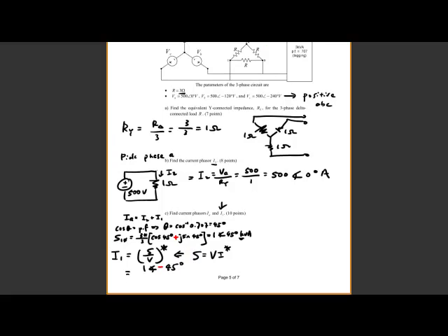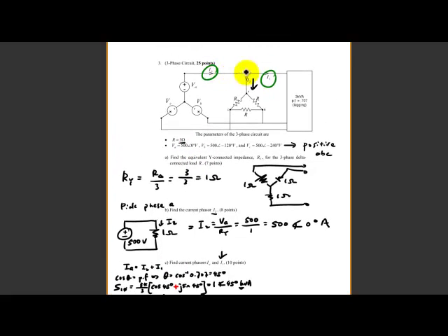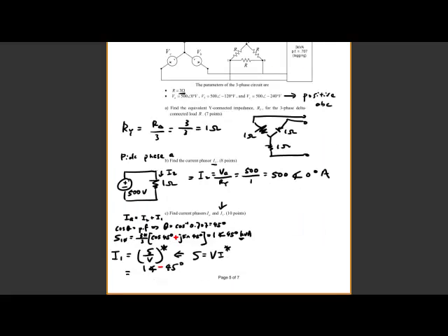And then you divide by the voltage. In this case, it will be just 500, because there is no resistor between these different parallel circuits. So all the voltage will be the same as the sending source. That will give you 500, right? And I think this is not just 1; it's 1k. Sometimes if you miss that, the solution will be totally wrong. So that will give me 2 with an angle of minus 45 degrees amperes in this case, right?